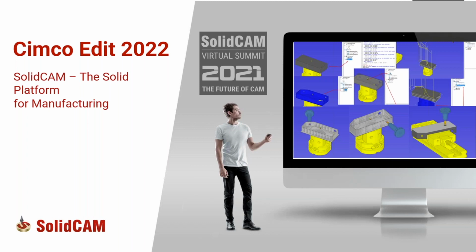Second, it can catch errors which are not visible in the CAM systems, because there could be an issue with the post processor that generated that error, or some other thing. But these errors are generally caught by CIMCO straightforward when you're running the simulation. However, all these years, as a standalone product, it was really very difficult. It needed a lot of work to get CIMCO to actually do a backplot.